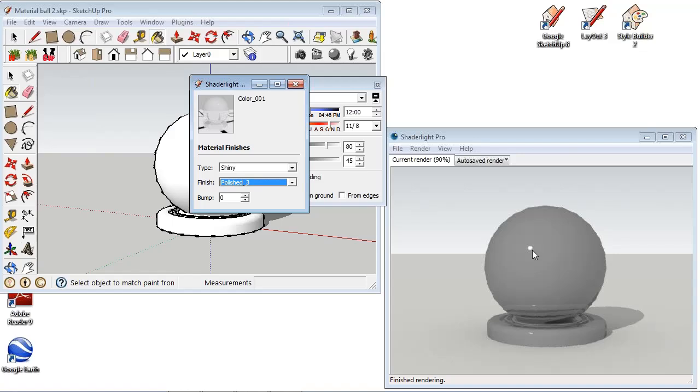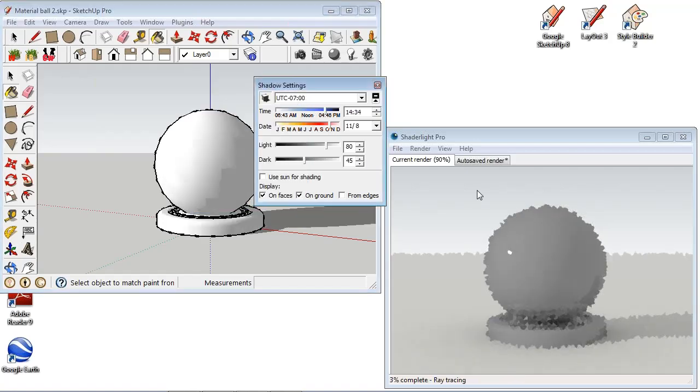So, that's the first thing you need to understand, that the SketchUp Sunlight is just that point of light. This also means that because it's a small point of light, the shadow is never going to differ from that hard edge. When we put the sun in the lower position, yeah, the shadow intensity changes, it becomes slightly lighter. But we always get the hard edge shadow, and that's simply because the SketchUp Sunlight is that single point of light.